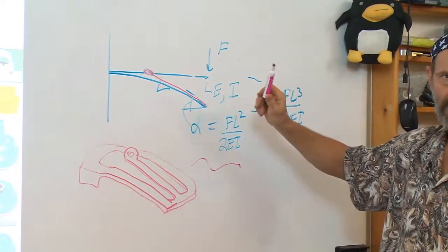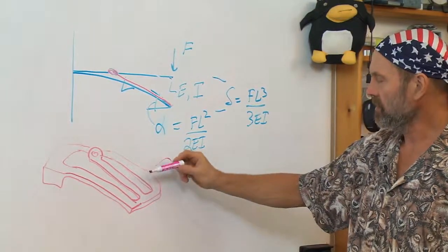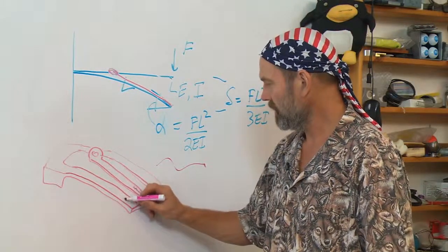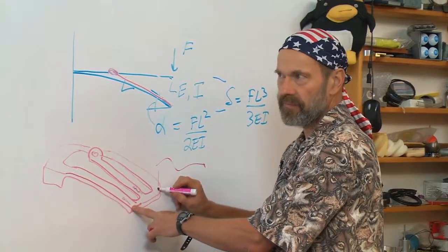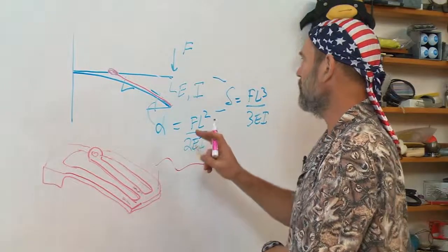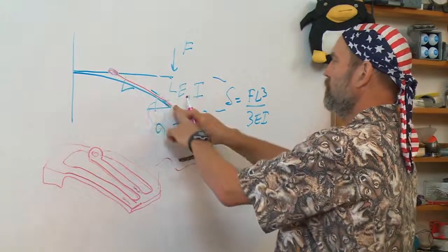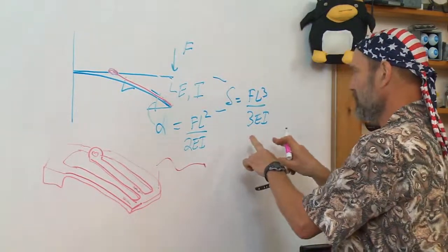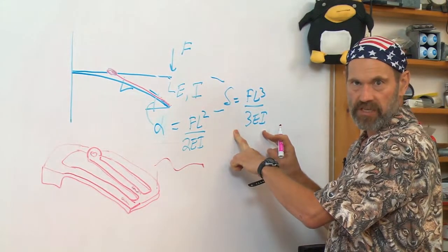Remember the principle of the Abbe error, Abbe offset. There's no forces on this middle beam. It is going to have the same slope as the side beams do, which have the forces applied to them, which means that there is some point where I can use this angle times some length to cancel, for this application, what is the parasitic error motion.